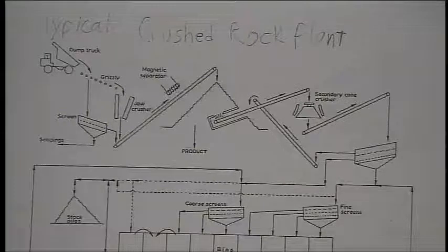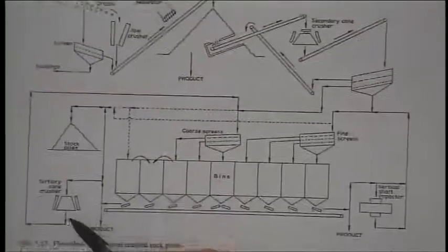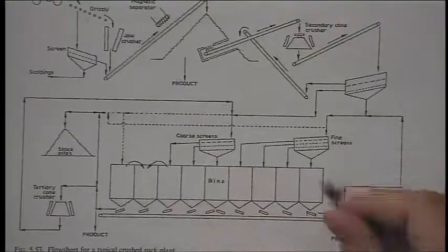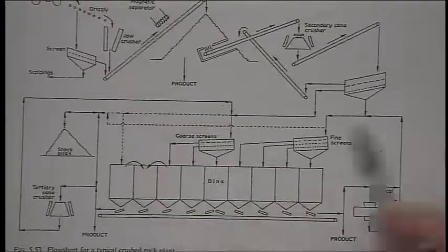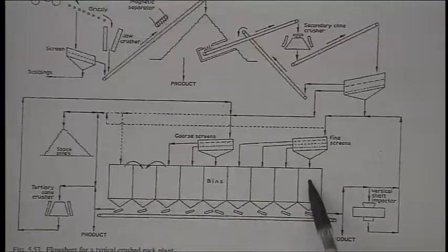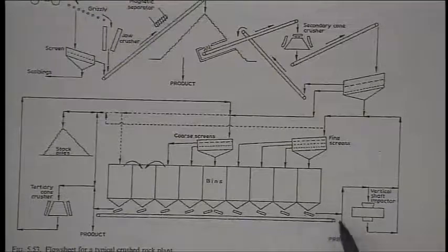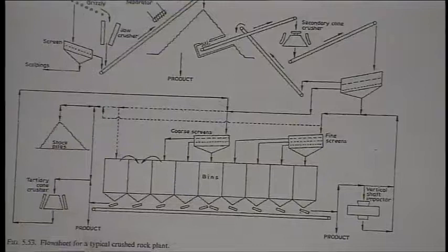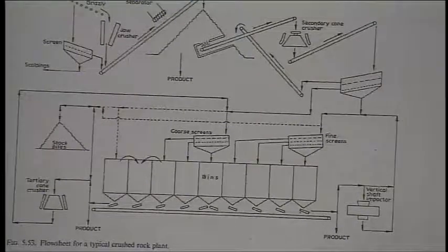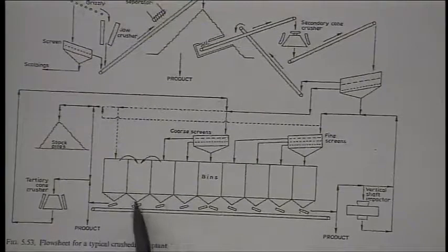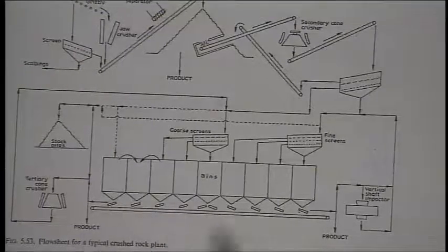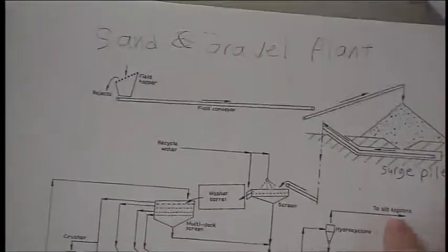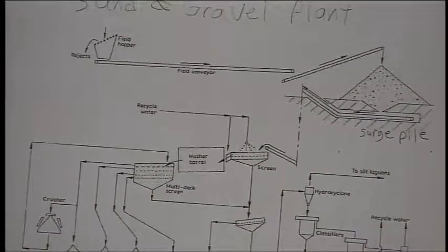And so what happens eventually is they go into bins, where they get sorted into sizes. And sometimes some sizes aren't typically what they want, so they may go into another crusher. There are many different things that happen, and you can actually combine your gradation and your products here too. A similar thing is done with sand and gravel.